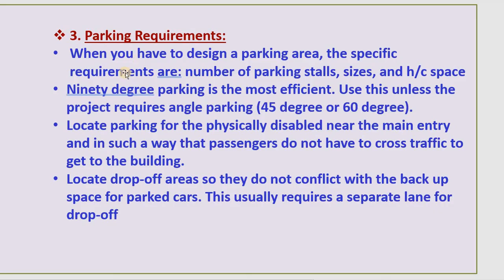Okay, so number 3, parking requirements. When you design the parking area, you need the requirements for the number of parking spaces, the size of the spaces, and handicap spaces. Usually 90-degree parking is the best, because it is the most efficient and yields the most spaces. Some projects require angle parking, 45 degree and 60 degrees. Sometimes you need to do that, but it is not as good as 90 degree.